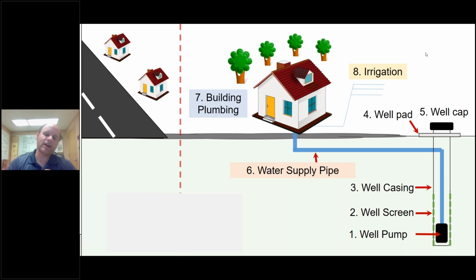In the Camp Fire in 2018, they saw that about 10 feet below ground, the PVC well casing was melted just because it's so hot how it burned above ground. We can also have irrigation systems that are on private property or commercial properties, and those can burn, and then the contamination can actually get sucked back into the distribution system. So when fires happen, you can sometimes have chaos take over, where you have infrastructure burning, you can have pressure loss, power loss, and you can have contamination, whether it be soot or debris, start moving into your infrastructure or being drawn in, and then when firefighters fight fires, they can actually drag it around the system.